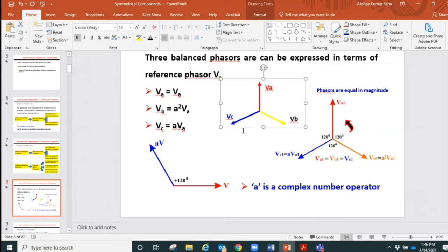The same thing can be said about the impedance. So far we have had only impedance Z. From now on, we will have positive sequence impedance, negative sequence impedance, and zero sequence impedance. So everything comes into the phasor diagram: we show the voltage, the current, the R, the X. Voltage, current, and impedance all have positive, negative, and zero sequence, so all of them need to be shown in the phasor diagram accordingly, so that when they observe it, they can understand what it is showing.